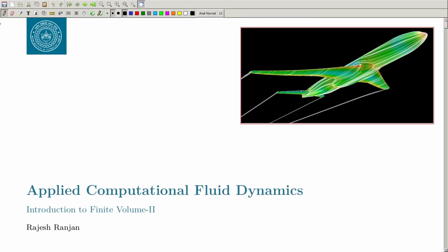we can use any kind of elements that we want. So, in 3D it can be polyhedral, like hexahedral, tetrahedral, prisms, pyramids, all these kinds of elements can be supported. In 2D it will be the polygon, triangle, then quadrilateral, all those kinds of elements are supported, right. So, this gives us the flexibility that we can use the finite volume approach for more complicated domains. In fact, this is the approach that is used most commonly when the simulation domain or the geometry is quite complicated. Okay. So, let us continue the discussion.